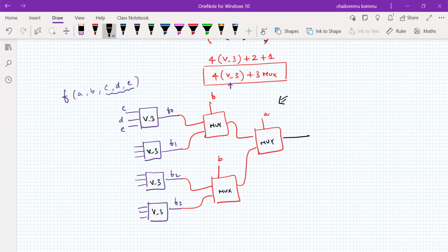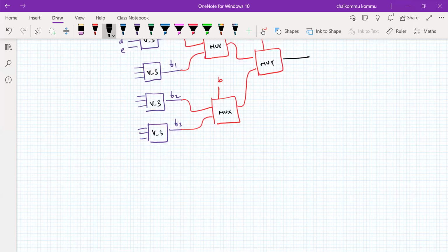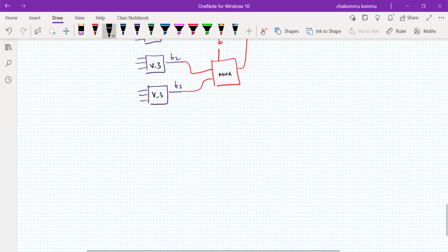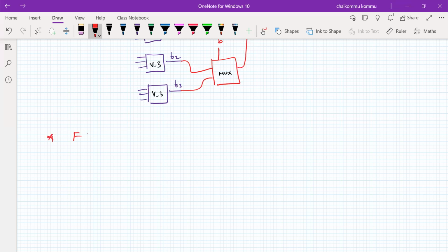Okay, so that is how this particular concept is very much useful whenever you are realizing functions in FPGAs. Each and every functional block, for example, what is the basic idea behind FPGAs? FPGAs consist of CLBs, right? CLB is nothing but a configurable logic block or combinatorial logic block, one and the same.